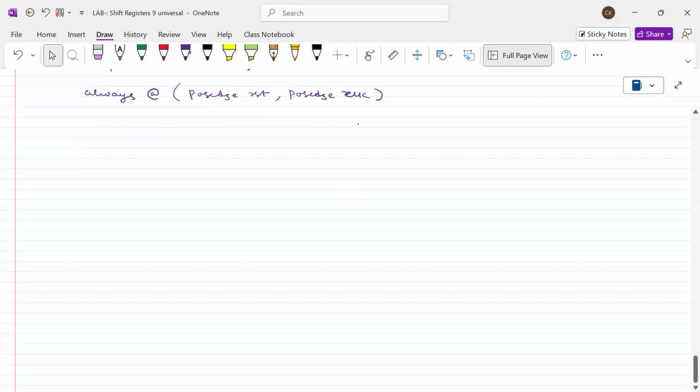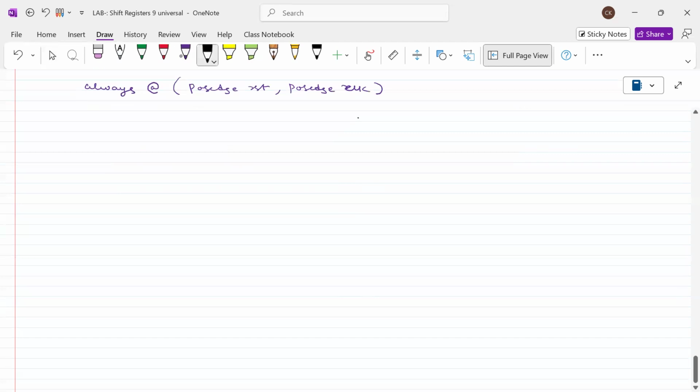Okay, now let us begin here. What is the first statement? We'll write: the first content of the flip-flop must be made 0, right? Otherwise, if it is unknown, whenever you clock, all the things will be unknown forever. You cannot change anything. That's the reason why